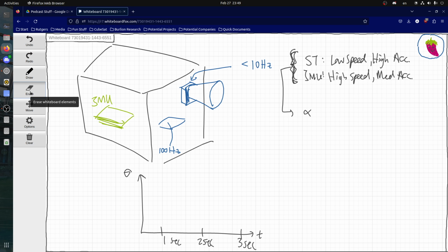Actually, I'm pretty sure that's one of the reasons why the Blue Canyon ADCS is so accurate. They design the system, they know what all the errors are, they know what all the uncertainties are, or at least they've placed bounds on them. Because they know the errors to a really high extent, they're able to design an optimal Kalman filter that does that job very well.